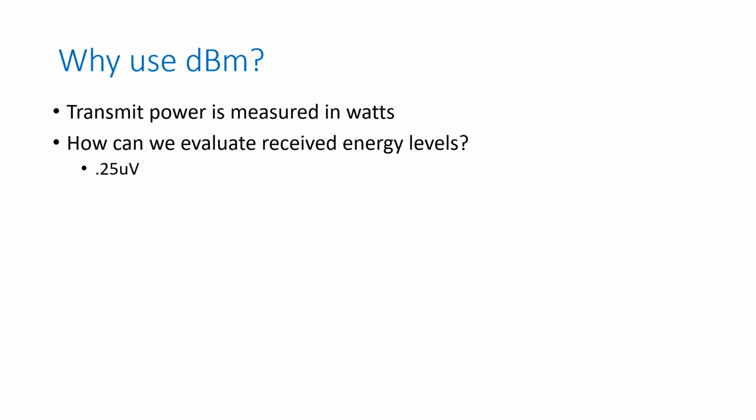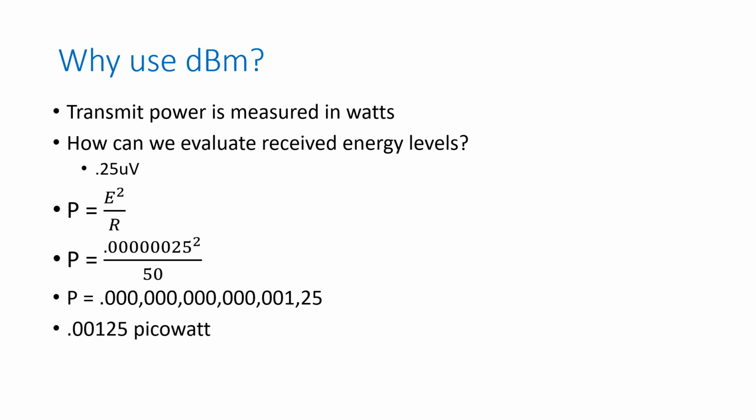Well, you might think, how do you calculate that? You take the voltage and square it, and you divide it by the resistance. What's the resistance? Well, it's the impedance of your radio. My 2-meter radio at the antenna connector on receive is approximately 50 ohms. So all I need to do is put the numbers in there and do the math, and I find out that's a picowatt. So I have a fraction of a picowatt out of your 100 watts. That's how much power you're putting into the front end of my receiver.